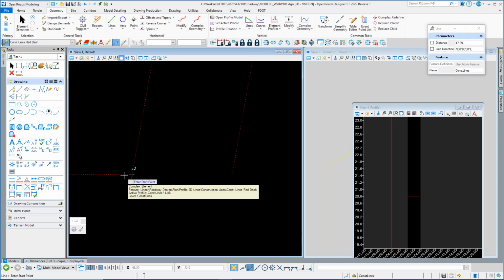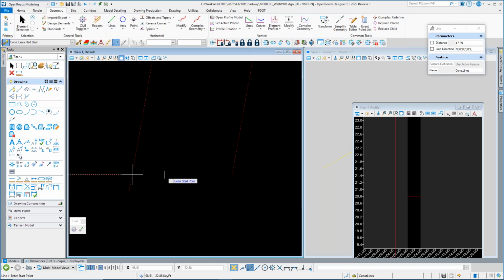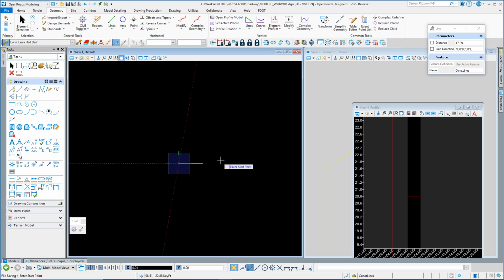And so I'll come in with this place line, our geometry line. I'm going to use AccuDraw again. And this one, I'm going to offset 0.04. So I'm just going to set the origin for AccuDraw so we can drag it out. And we can lock out AccuDraw and key in our 0.04 and enter. So that kicks us off just that little bit, the 0.04 off of that target.